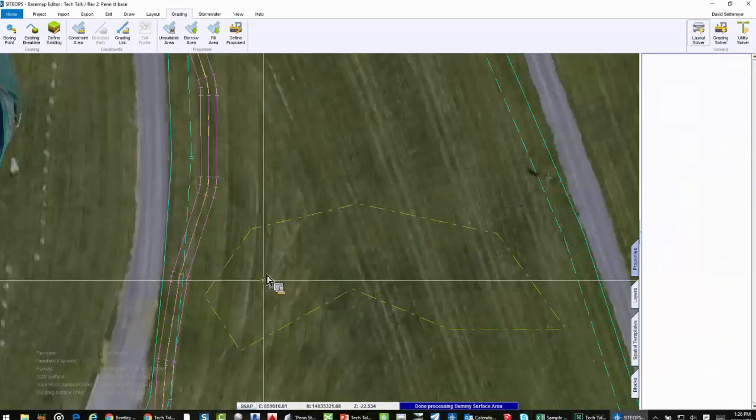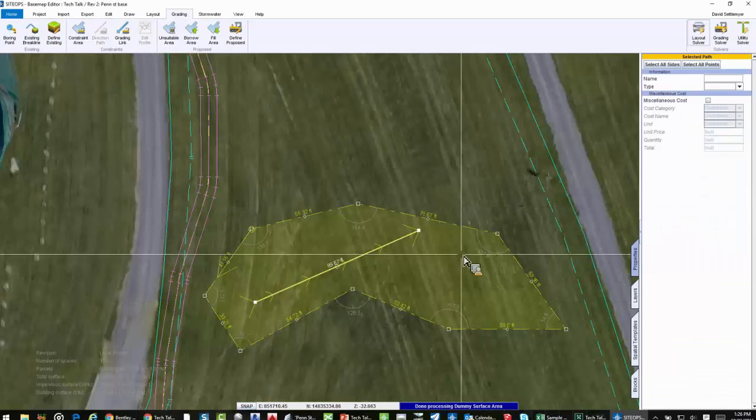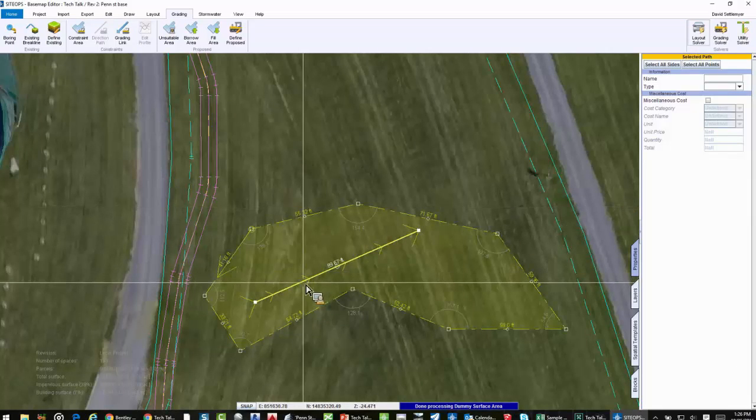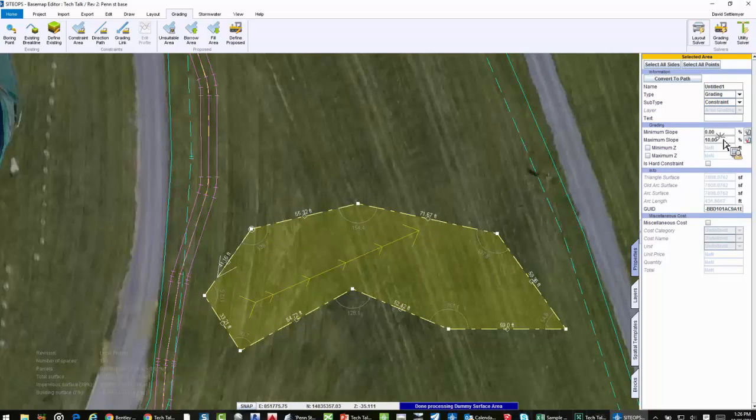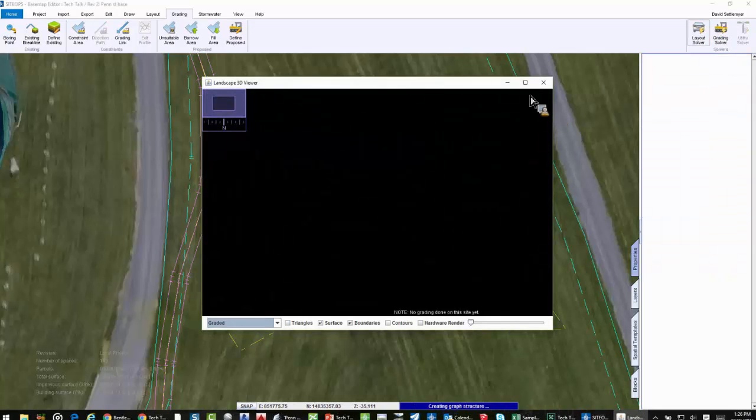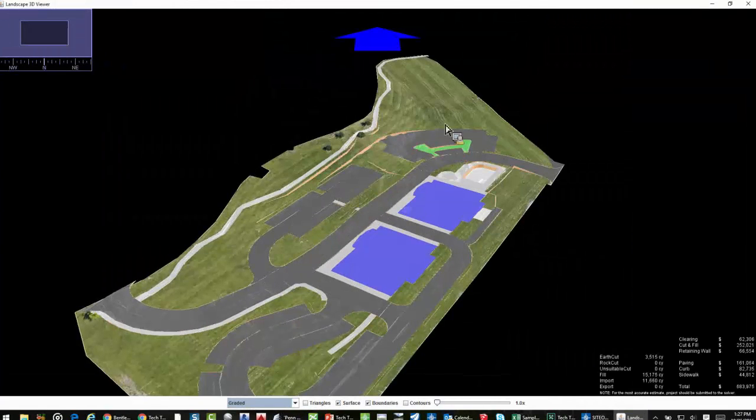We can actually set a grading direction. I want it to grade from southwest to northeast, and I want it to grade at 5%. Don't want it to think, don't want it to do. Sort of like an athletic field, we have to grade them a certain way. We can't make a pitcher's mound in a hole. It has to be up.